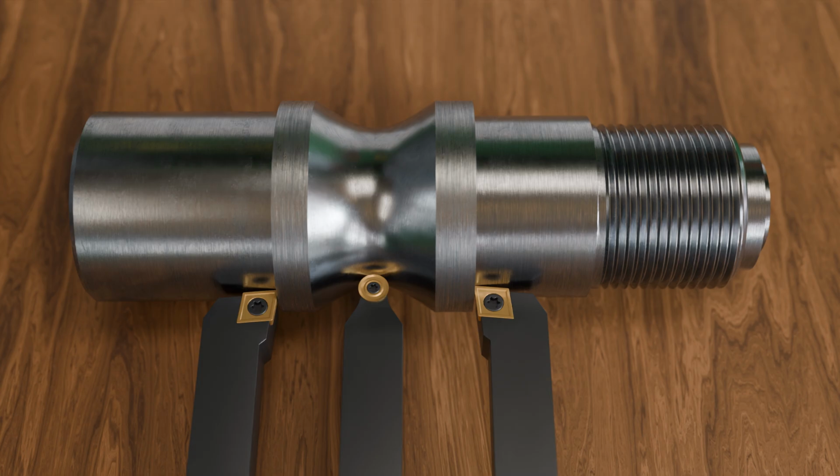They are roughly classified into left, right, and neutral turning tools. Mostly, right turning tools are used, which create the desired geometries on the workpiece from the right side. Left turning tools allow machining the workpiece from the left side without having to reclamp the workpiece. Additionally, there are neutral turning tools that enable machining the workpiece from both directions. This is, for example, the case in contour turning, where any shape is produced on the workpiece. Neutral turning tools are also mainly used in grooving and parting operations.